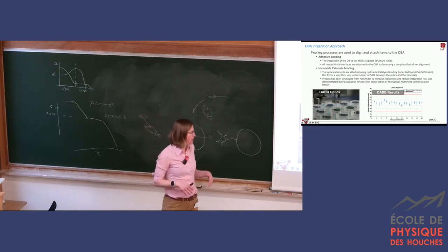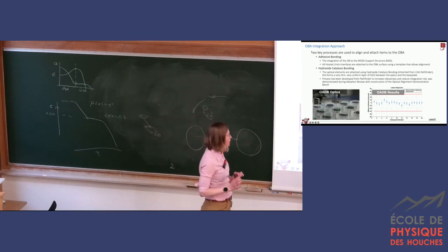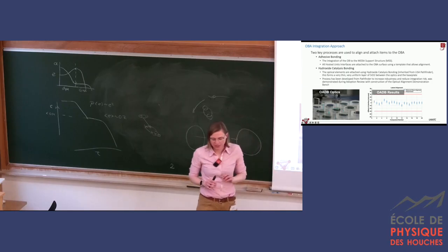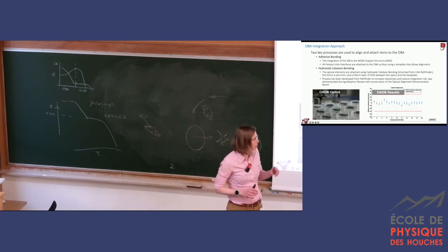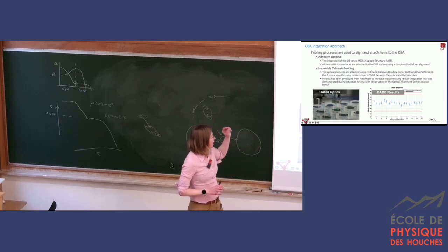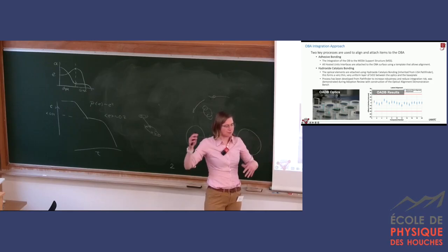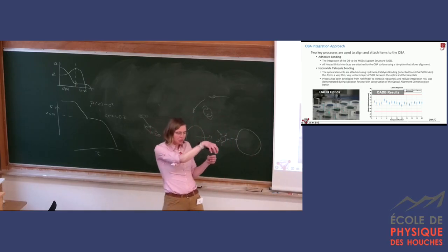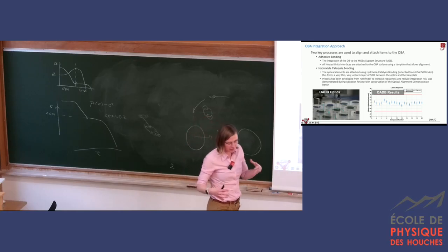For LISA Pathfinder, it was done by hand, but it's not practical because we have to build something like 10 optical benches, and they are both sided. So you can see already a little bit of an issue here. Optical benches are made in the UK. It's 2 institutes, UKATC and University of Glasgow, that are responsible for this. They developed a robot-assisted bonding technique, which is basically a robot arm that has a hexapod that precisely positions the optics. And then the rest has to be done by a human, but it already supports a lot of this.